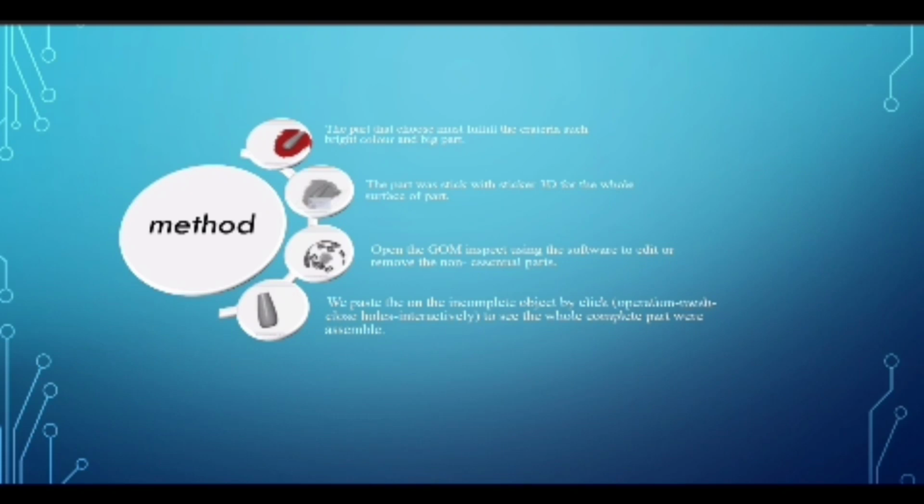The part was stuck with 3D stickers over the whole surface of the part. This is to make sure that during the scanning, the 3D scanner can get an accurate, precise result. The stickers function to make sure the pictures that are scanned do not shift or separate when scanning from other angles, to get the whole part.